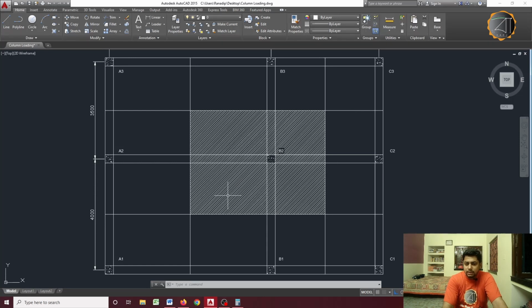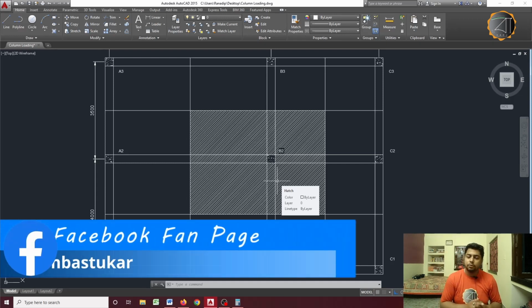We will be having the load of this slab, then the floor finishing works on this slab, these beams which are running in perpendicular direction, the rib of that beam, because a part of the beam is already included in the slab itself. So, whatever remaining part, the rib of the beam which is lying below the slab, we have to calculate the weight for that also. Next is the column stem itself, the portion of the column between the floor level and the beam bottom level of the next higher floor. The load from that column part we have to take.